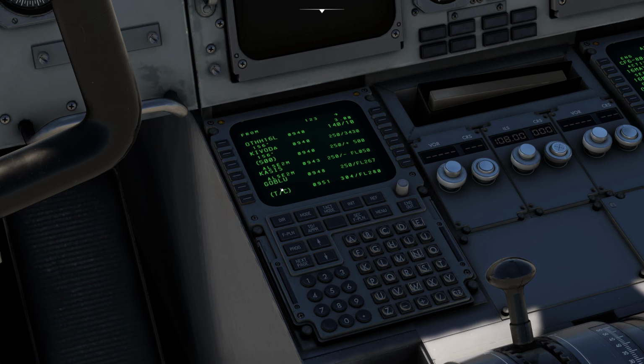So you have these all. Now as for the departure procedure, initially it was not showing, as now I've selected the departure procedure. The SID is shown, and all the waypoints this SID will follow. Then after LSEM, which is part of the departure procedure, you see airways and waypoints. And then you have different flight levels and speeds over here. At this point, let me give you a little bit of introduction on how to read this.